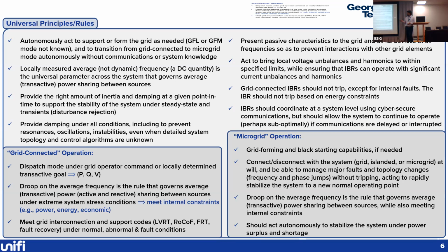And the point which connects to that is being able to connect and disconnect with the system kind of at will. That is something which we will see as a uniqueness between distribution and transmission, where the aspirational goal is, if there are inverters, at least in the distribution system, that keep disconnecting or connecting back, they shouldn't cause a disturbance on the system, which means if the grid forming inverter is resynchronizing back to the grid after a trip, it should do so in a seamless manner.